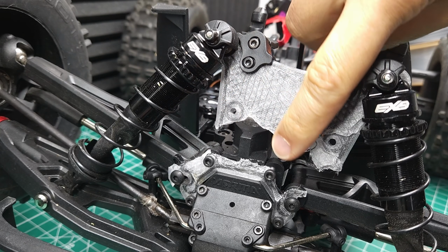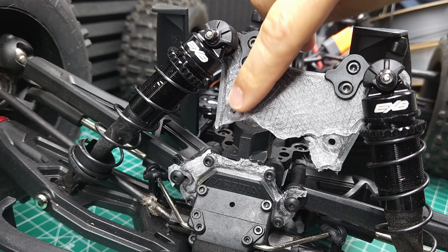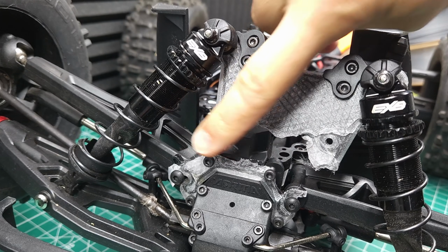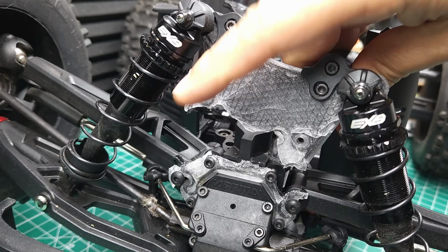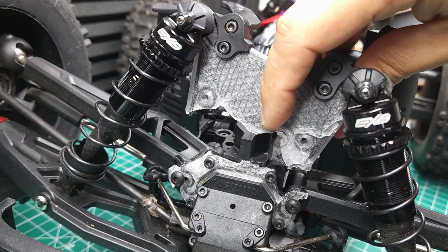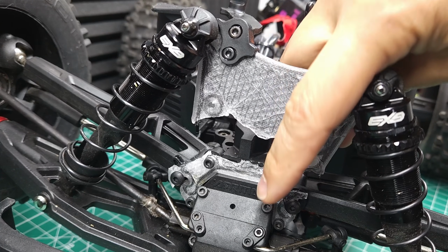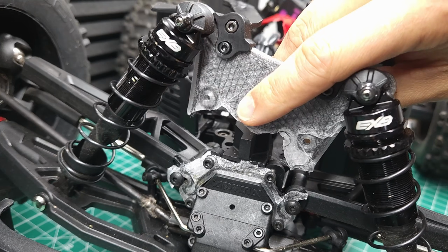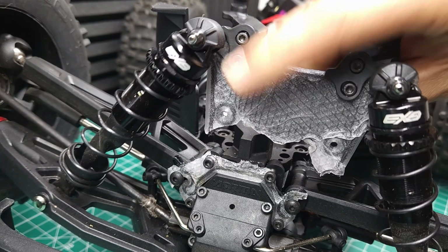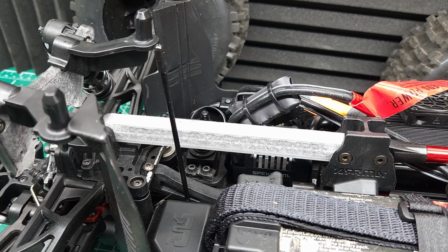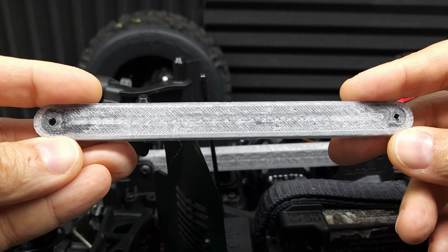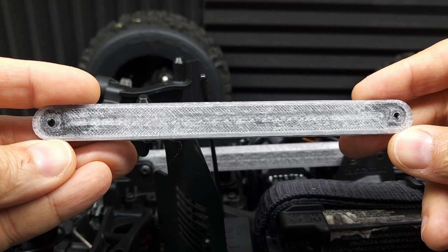Where this split apart is the spot that has the least carbon fiber reinforcement. All the infill's up here. There was no reinforcement around these two screws, and so it really only had to break this little bit on both ends. If I designed this again in the future, I would do it completely differently, and it would have a lot more strength between the top and the bottom here. And I suspect it would be a lot stronger, but even this survived way longer than I expected it to. However, the tower-to-tower brace still looks absolutely perfect, so we really have no reason to swap it out for this much stronger part, so how about we try to lift a few thousand pounds with it?